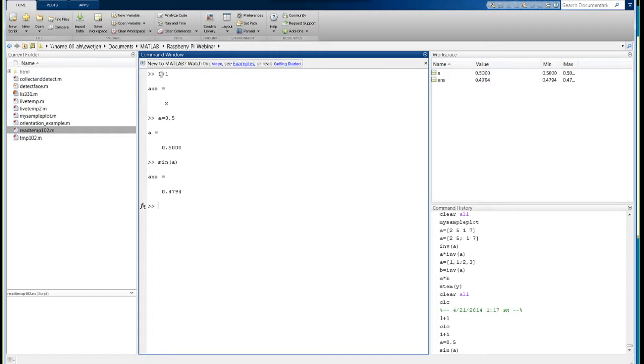One thing to note is that everything is a matrix in MATLAB, and that's actually how MATLAB got its name, it comes from matrix laboratory. So I can create a row vector instead of just a single scalar like I was doing before, and I can say A is equal to, using the brackets, 0, 1, 3, 5, 6, 7, 12. And when I press return, you can see now I have a row vector. And if I look over in the MATLAB workspace, it will show me that row vector here, A, and those are the elements of the row.